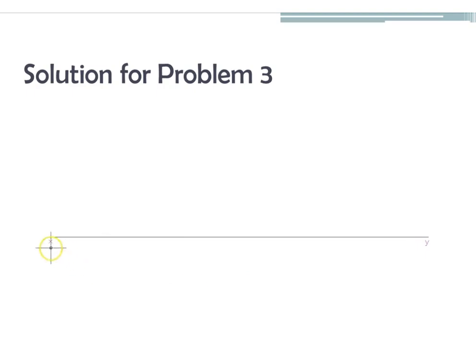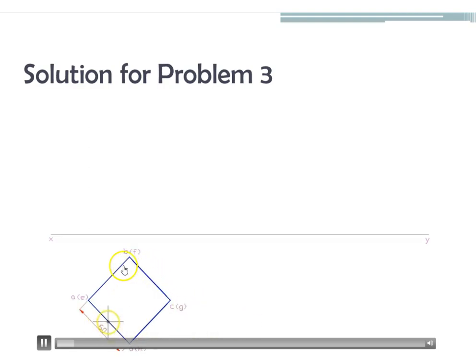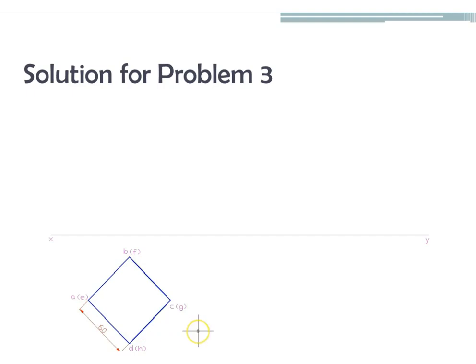So we'll start by drawing the xy line and then the solid in a particular position, that is a cube in this particular position which we have seen before, so that the corner is on one side, and then from there we project the corners onto the top view to get the top view.